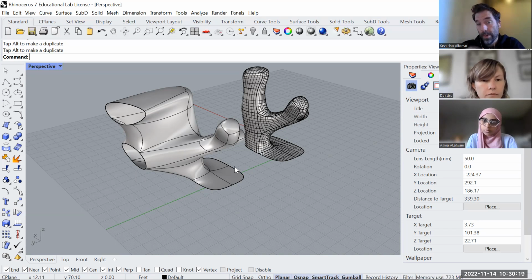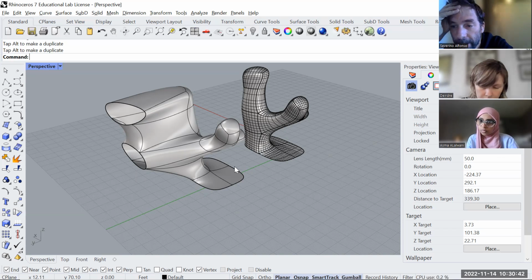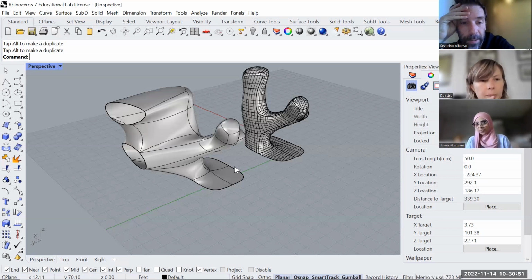And then, if you want to do the material rendering, I would just apply a material that has wood lines and a black and white image associated to the transparency that will tell Rhino or Revit this is transparent, this is wood. No? You have used materials in Revit that have wood and transparent, no? Okay, nice. Otherwise, I can help you with that one too.